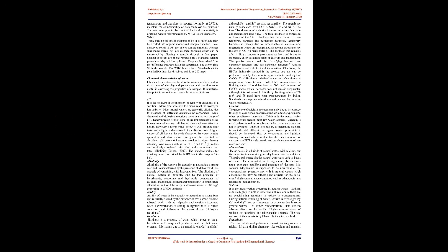Among the methods available for the determination of hardness, the EDTA titrimetric method is the precise one and can be performed rapidly. Hardness is expressed in terms of mg/L of CaCO3. Total hardness is defined as the sum of calcium and magnesium concentration. WHO has recommended a limiting value of total hardness as 500 mg/L in terms of CaCO3, above which the water does not remain very useful although it is not harmful.